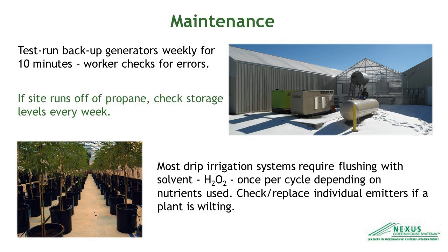Then you have your equipment outside of the greenhouse. Most often I tell people to be mindful of their generators. You want to make sure you run your generators on a weekly basis if you have them, backup power. They're extremely important for maintaining temperatures in the greenhouse during extreme weather, and that tends to be when the power supply is not reliable from the grid. So every week you run for about 10 minutes and make sure our workers are around to hear them run.